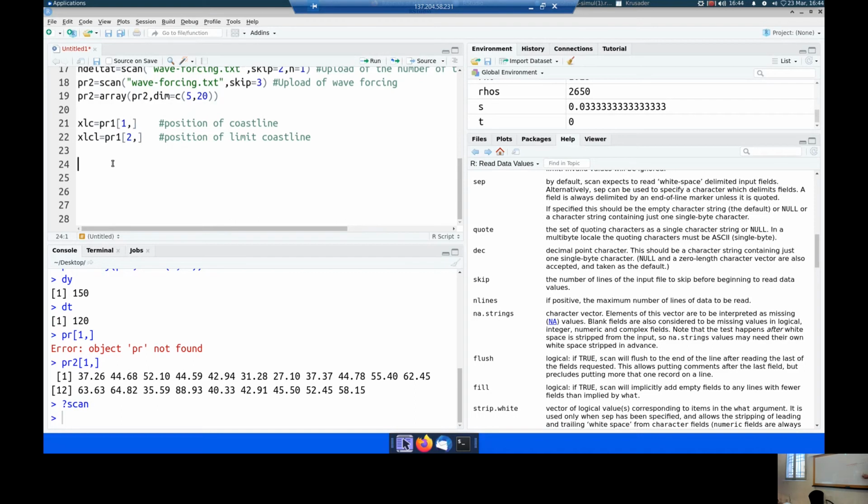And here you have nothing getting in, and therefore, if you have a sediment transport potential greater than 0, which is likely because otherwise you wouldn't put the groin here, you get this shape, which is erosion. That is what happens with groins: you have something like this, and then erosion there.